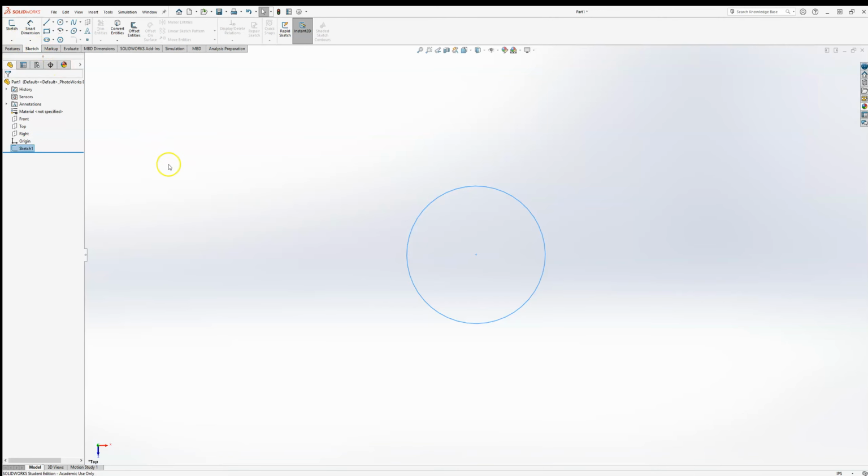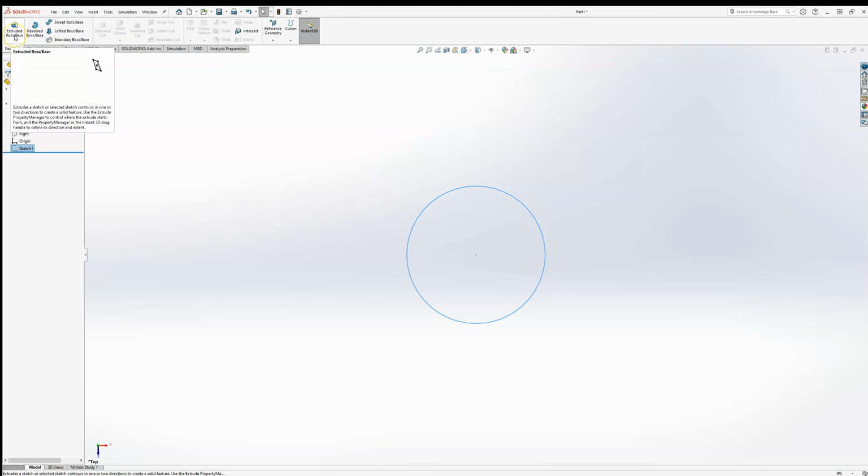And so we talked about SolidWorks, this feature tree developing. So now we've got our first feature, and it's the sketch. You can see if I hover over it, it references the origin as well as the top plane. And so with it selected, notice I've got it still selected, I'm going to go straight into the Features tab, and I'm going to go to a Boss Extrude.